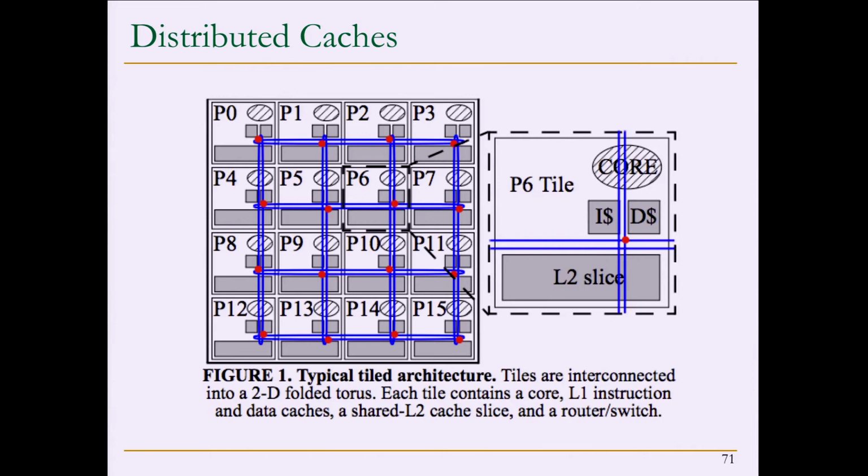you're traversing a lot of your core, right? So there are a lot of issues that are caused by distributing the cache. But this is a more scalable approach to designing a multi-core system. Now you're really tiling different cores and different components and stamping those tiles, if you will, and hopefully getting better performance. But now you need to manage the cache even more intelligently than what we've discussed. Because now there's another parameter, which is the distance, and also the contention, and how long it takes to access